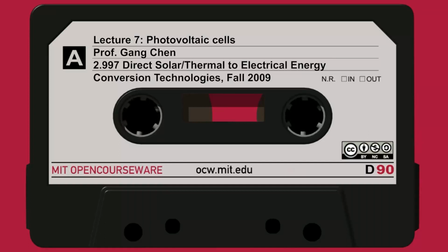Okay? And of course, as I mentioned, this is the curve I drew. You can see electron diffusion. Because on this side, when the hole diffuses to this side, there's no more electron, right? So the electron will recombine with the hole, so there's less electron flux forward. So if I look at the electron current, it decreases in this recombination region. And then I look at the hole current, right? On this side, the hole current decreases in this region. That's where the supply recombines with the electron.